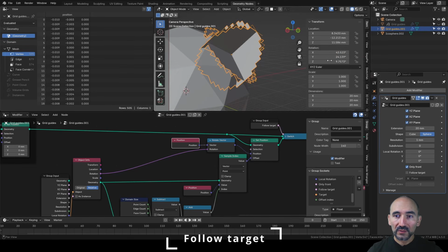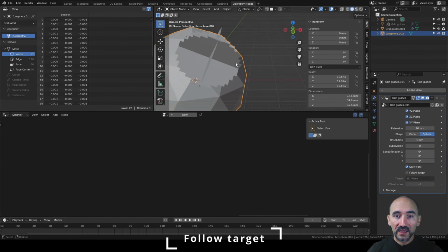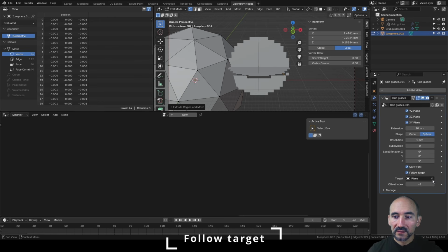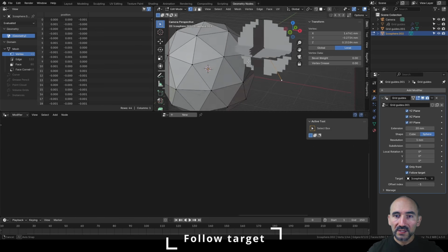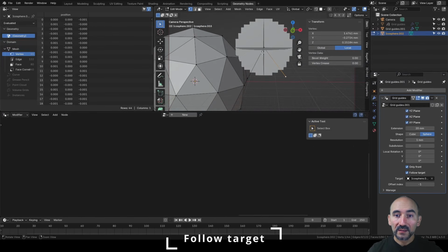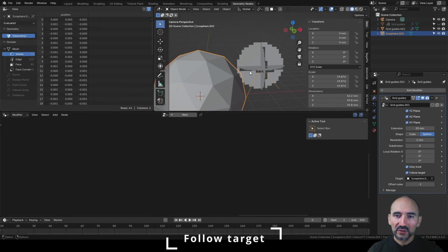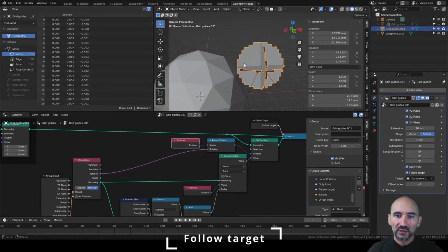You can see the right rotation on the object itself of my guides. And now if I take my icosphere, take one vertex, extrude it one time and a second time, and I enable the follow target, selecting the new icosphere object and selecting -1, you can see the correct position of my guides. But I lost the rotation of the alignment started from this face. So the relationship of the rotation is maintained if I rotate the object, but the start rotation based on the triangle I snap it to is lost.